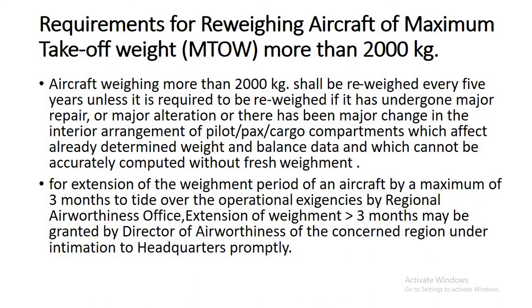Okay, and sometimes you are running an airline and it's a busy schedule. You're not getting enough time, instruments or persons to conduct weighing of the aircraft in the duration. Then, due to operational exigencies, you can extend up to 3 months. You have to get approval from the regional airworthiness office for 3 months.